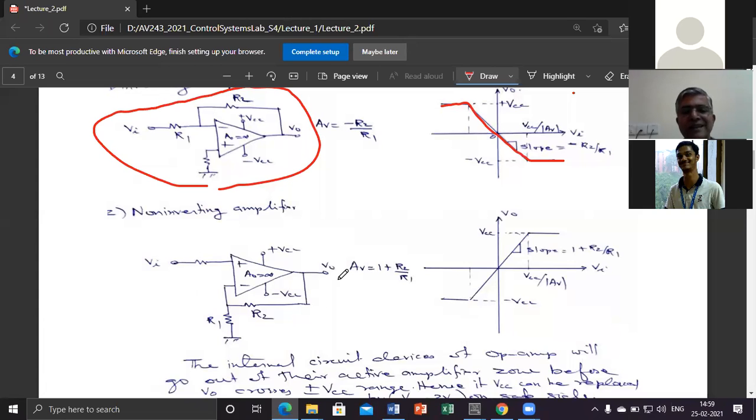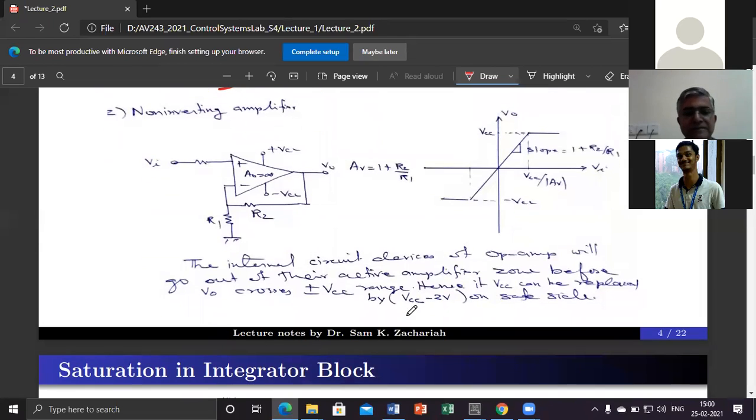This is a pure static circuit because the present value of the output voltage depends only on the present value of the input voltage. History is not important here. Hence, if you change the direction of the input voltage, the output will trace through the same curve.